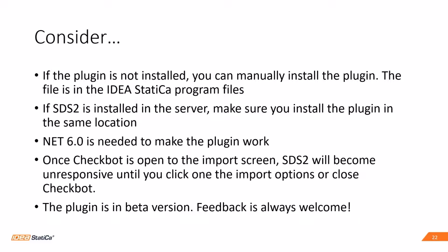Also, .NET 6 is needed to make the plugin work. So if you don't have it on your computer, maybe that is the issue, okay? So you need to install .NET 6.0. You can Google that and download it for free, okay? And the thing that I mentioned, once Checkbot is open in the import screen, SDS2 will become unresponsive, okay? So until you close Checkbot, you cannot go back to SDS2 and work in SDS2, okay? And again, the plugin is in beta version and feedback is always welcome. So that is how we learn from the users and share all this information with you, okay?